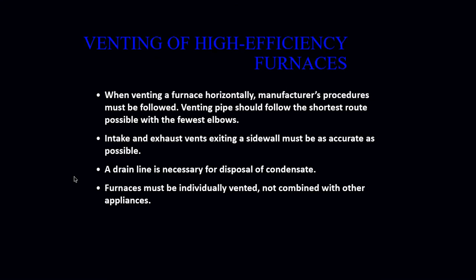If we do not follow these simple rules, we are going to run into problems with ignition. A lot of our high efficiency furnaces today have pressure switches, sail switches, all sorts of safeties in there. If we are not properly draining our flue pipes and our furnaces, we may run into a problem where a pressure switch may not close properly to send the signal for ignition. Furnaces must be individually vented, not combined with any other appliance.